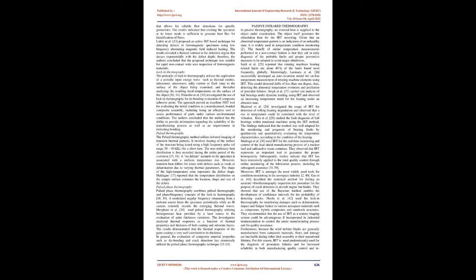Mabruki et al. performed both numerical simulations and experimental studies using vibrothermography for detection of fatigue cracks in a steel compact tension specimen. The model revealed that the specimen's temperature increases at the crack vicinity according to the excitation frequency and is modulated due to nonlinearity induced by the crack. The experimental results confirmed the potential of vibrothermography as a quick NDT&E method able to detect surface cracks.